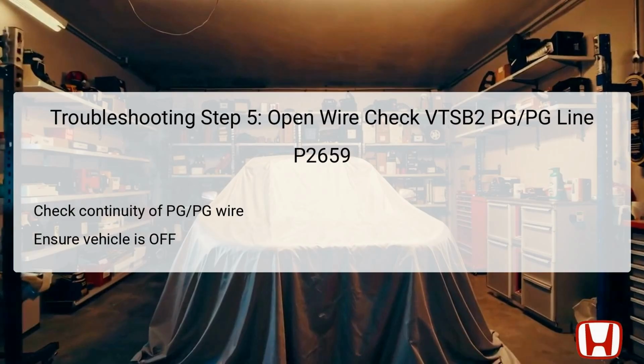If continuity is confirmed, the wiring integrity is assured, and the technician can move on to the next step. Conversely, if continuity is not present, there may be an open circuit, which necessitates repairs in the wiring between the rocker arm oil control solenoid A, bank 2, and ground point G101 to restore proper electrical function.